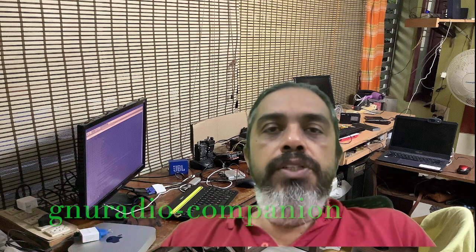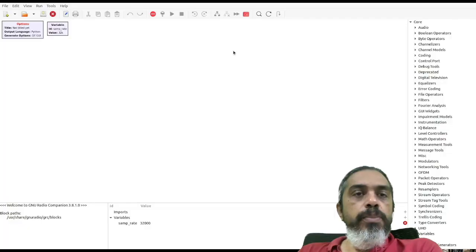On my Ubuntu system, I can click on the GNU Radio icon from the applications, or I can open up a terminal and launch the program by typing in GNU Radio Companion. So let's see how it opens up. GNU Radio programs are called Flowgraphs. Your Flowgraphs are built from different blocks available in the program.